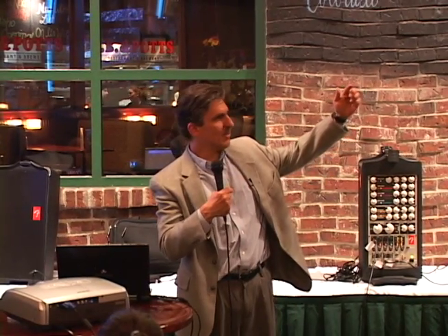But there's only so much energy in the wind before you stop it, and the best way to get it is this horizontal axis machine. And all these ideas about putting cowlings and things around the machine, they just don't pay for themselves, because all you have to do is add another meter to the blade, and you've increased your swept area by an awful lot as you go out, and that's not very expensive to do.